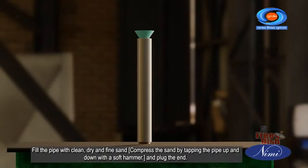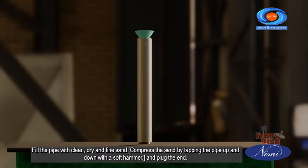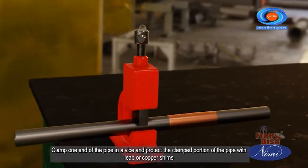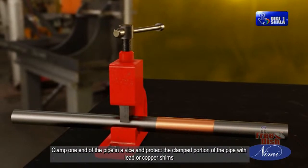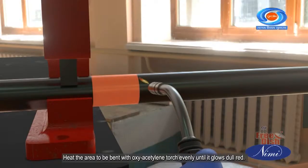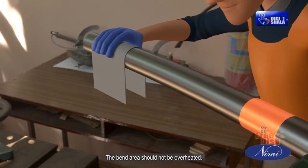Fill the pipe with clean, dry and fine sand. Compress the sand by tapping the pipe up and down with a soft hammer and plug the end. Ensure that the entire pipe is filled with sand. Clamp one end of the pipe in a vise and protect the clamped portion of the pipe with lead or copper shims. Heat the area to be bent with an oxyacetylene torch evenly until it glows dull red. The bent area should not be overheated.